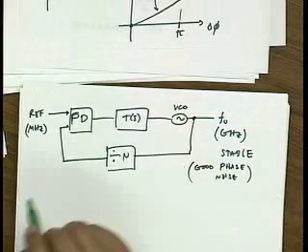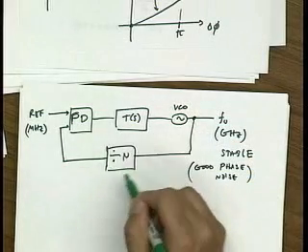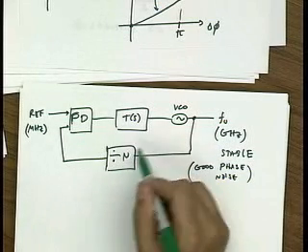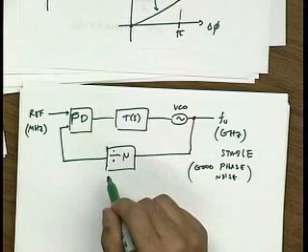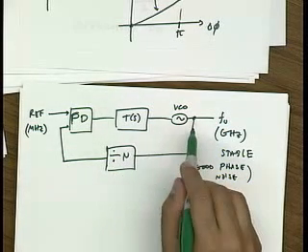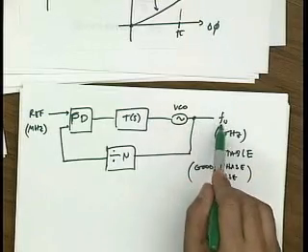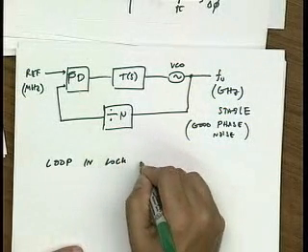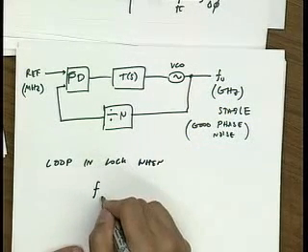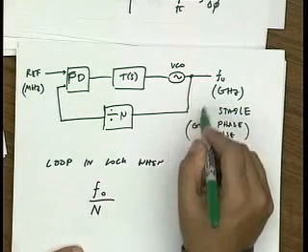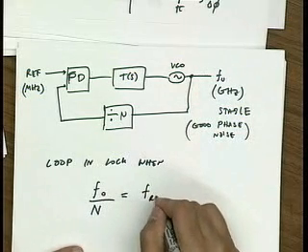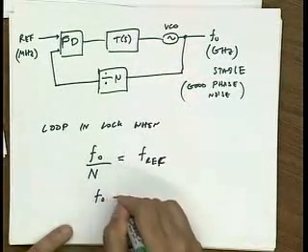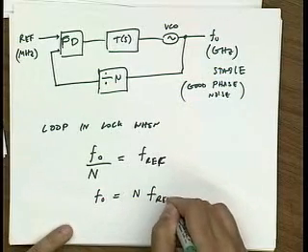And another benefit that you get is that because this divider is also a digital circuit, essentially, I can change the division factor, right? I can go from a division factor of 100 to 101. That means that I can control the output frequency. So basically this loop is locked when the output frequency divided by N locks to f-ref. That means that the output frequency is N times f-ref.